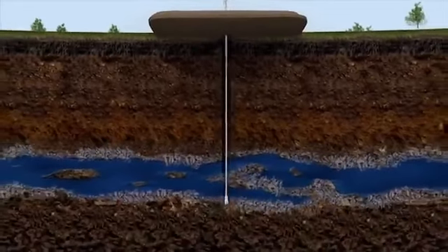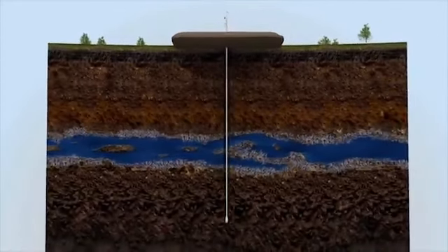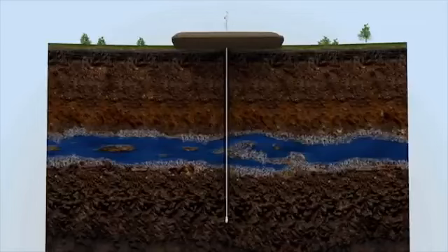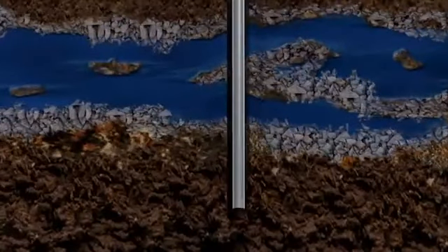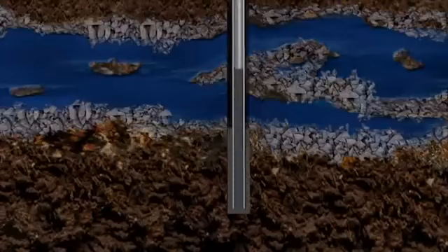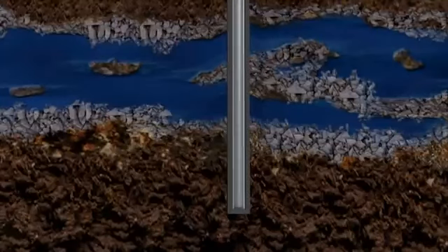A hole is drilled straight down using freshwater-based fluids, which cool the drill bit, carry the rock cuttings back to the surface, and stabilize the wall of the well bore. Once the hole extends below the deepest freshwater aquifer, the drill pipe is removed and replaced with steel pipe, called surface casing. Next, cement is pumped down the casing. When it reaches the bottom, it is pumped back up between the casing and the borehole wall, creating an impermeable additional protective barrier between the well bore and any freshwater sources.